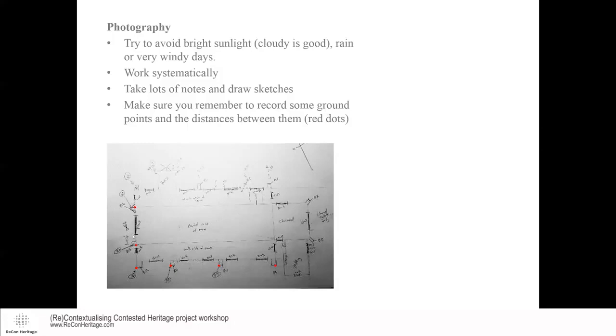I was lucky because this building has a nice 90-degree angle here, and so I can get a nice L-shaped set of points, and that's ideal because I can say this point is 0, 0, X and Y. I can say these are all in the X direction, but they're 0 in Y, and all these are 0 in X, and distances in the Y direction. And that makes it nice and easy to define the points.